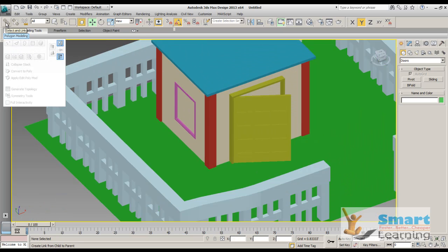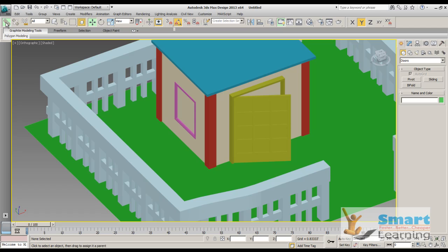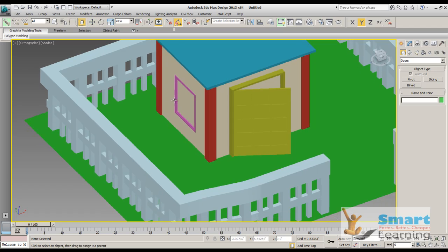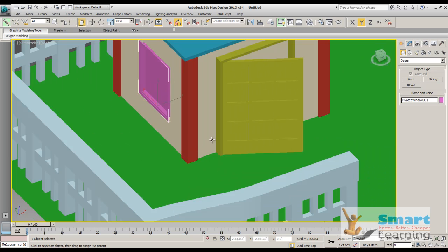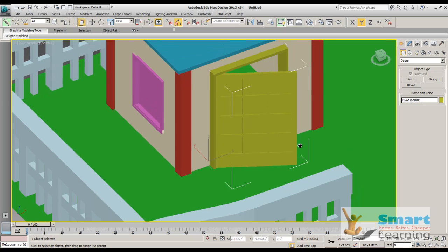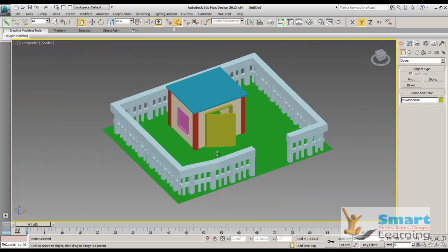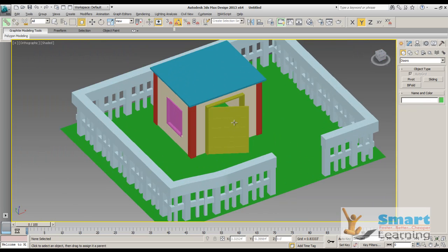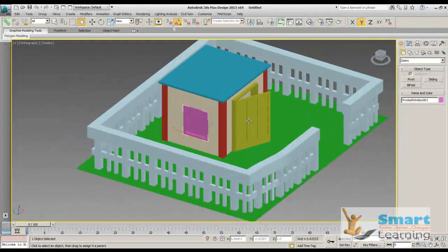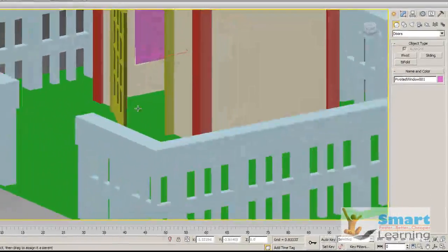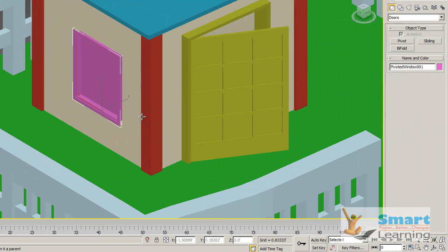So here you can see this is the link option, so which you can directly select and link and select the wall. So this will be linked just like that. Select this and select the wall. This will be linked and automatically the opening will be created by selecting this link option. Now you can see you have automatically cut out here as well as here also. From the inside you can see it is properly fitted.